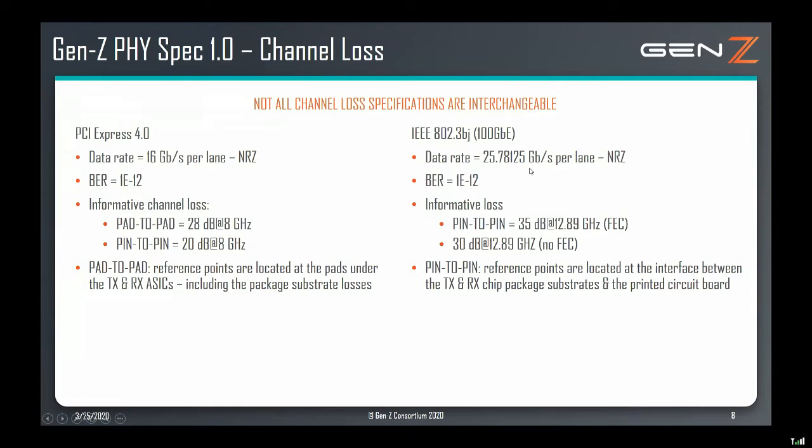Now, the reason for doing this is PCIe is very targeted, and it has a lot of applications for things like connecting up to a memory or a processor, specifically connected to endpoints. And then Ethernet provides longer reach, which means you can have longer traces or cables or more connectors in the channel. And so that provides more of a fabric connectivity.